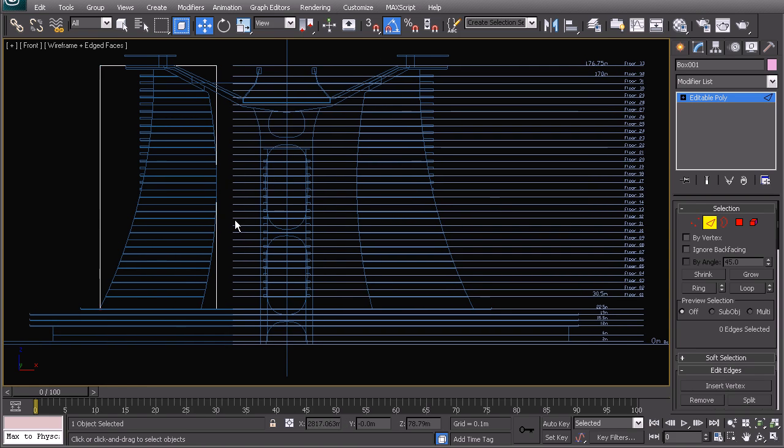Next, I'm going to set out the main heights. I'm just going to select that there. So I'm going to create connect, press W to make sure you're in the move command. And then I'm going to set the top floor, because the distance between all of these floors is exactly the same, and it's just this one up here and the difference between the podium and the first floor that is slightly odd. So I'm going to just set up those two lines, and then we're going to connect with a continuous set of equally spaced lines once we're done with that.